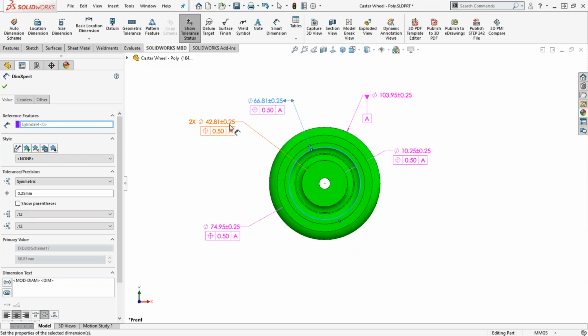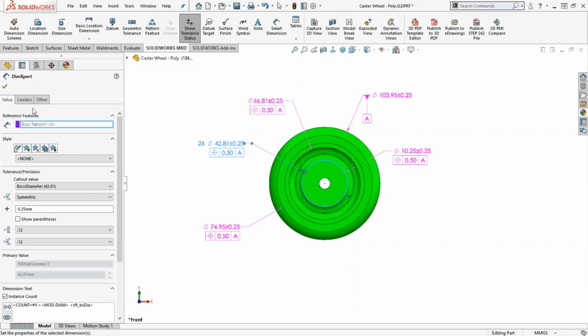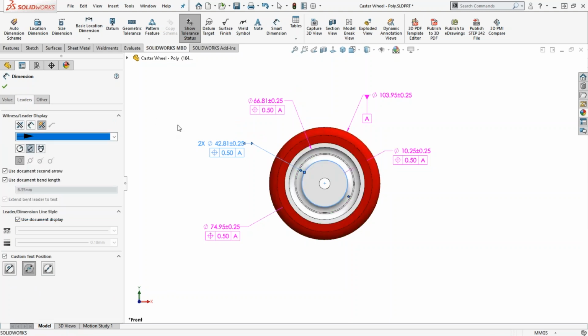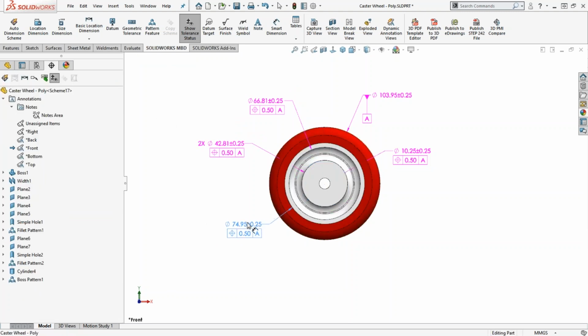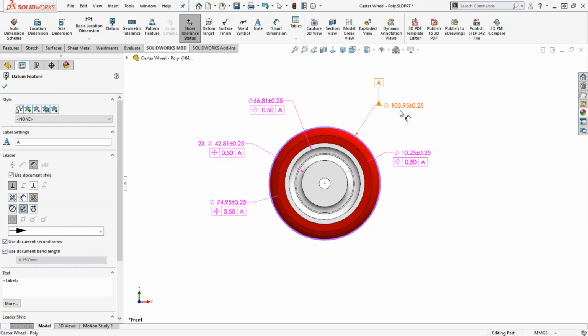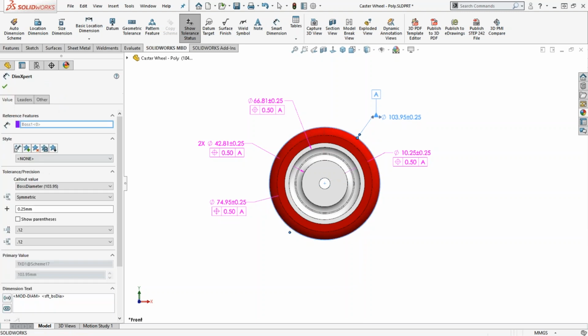So we're going to capture views representing these callouts. See, in this case, I want to move from this dot leader to arrow leader. Doesn't really matter how this stuff is organized, just in a way that's clearly presented. Maybe I can move this datum up there instead of down. Makes things a little bit easier.